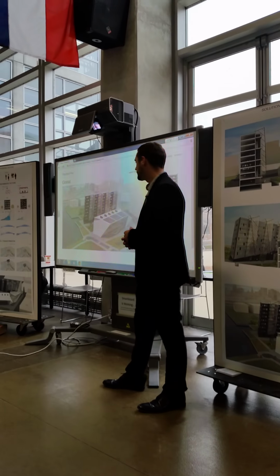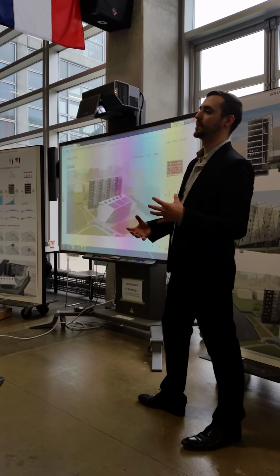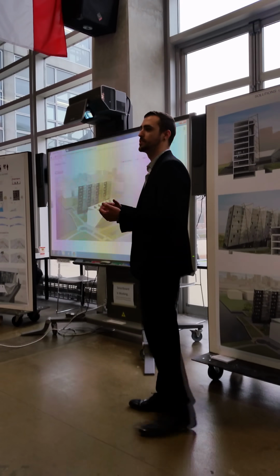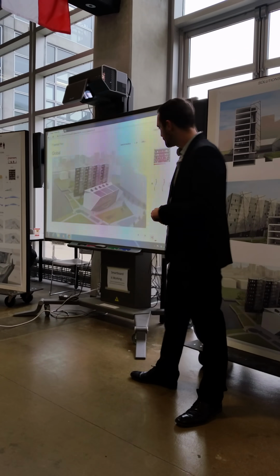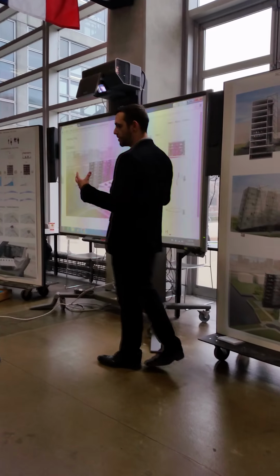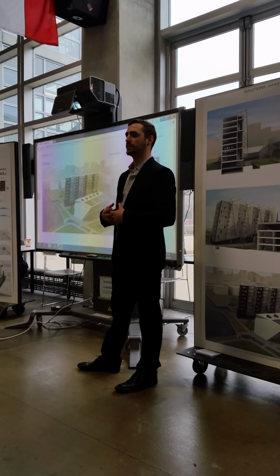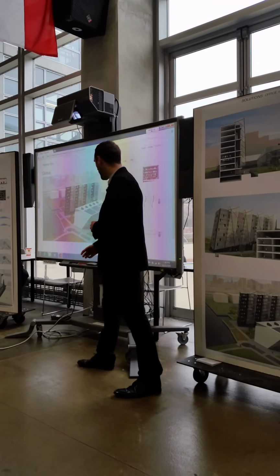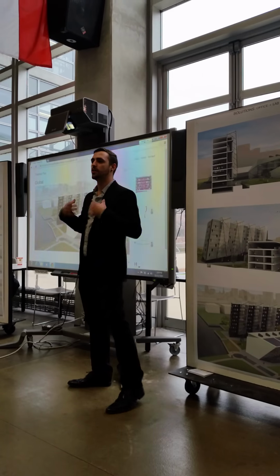So then, I'm going to go through a sequence of how this building reacts seasonally, and how we can start to use some of these strategies and techniques that are outlined in the video. In the summer months, it gets warmer, so we need to worry about the building overheating. These massive concrete surfaces, all these interior spaces, all this glass, they're all going to overheat.